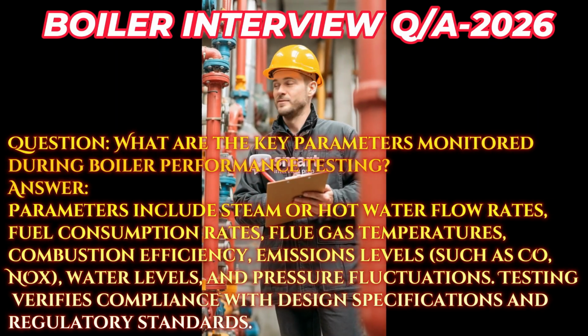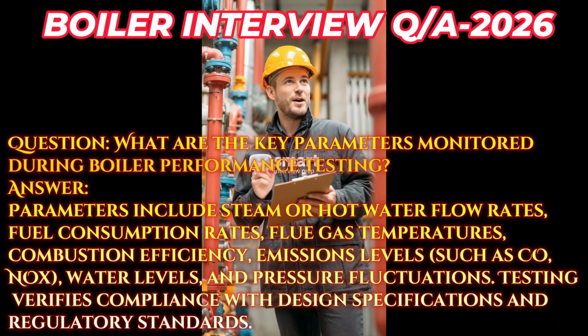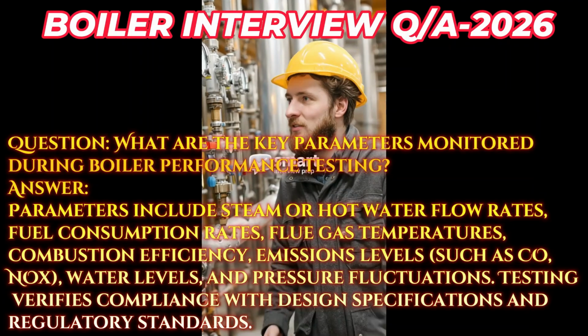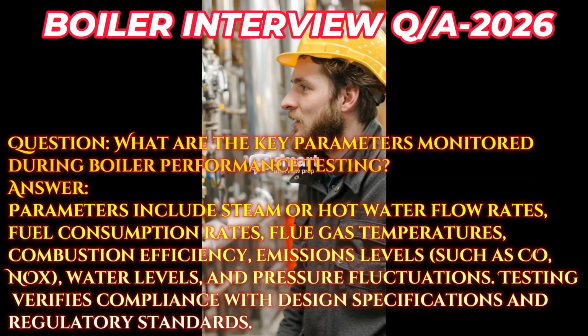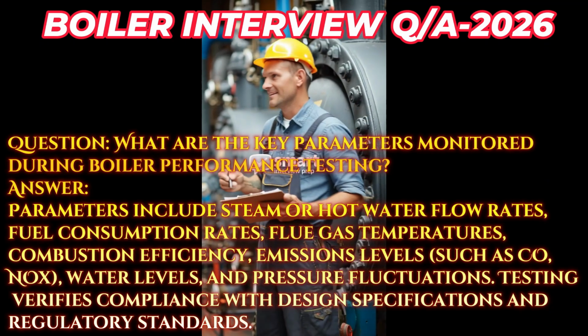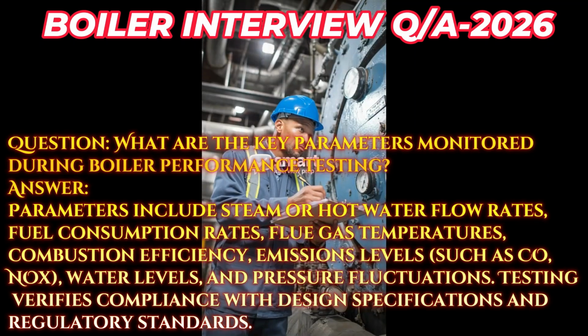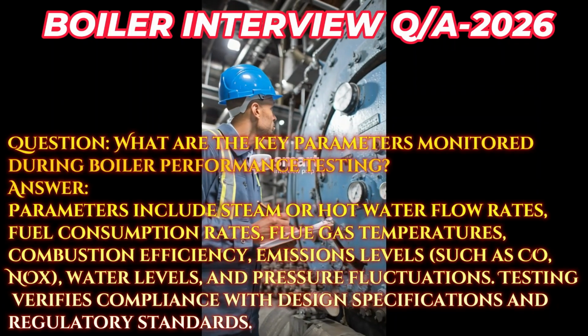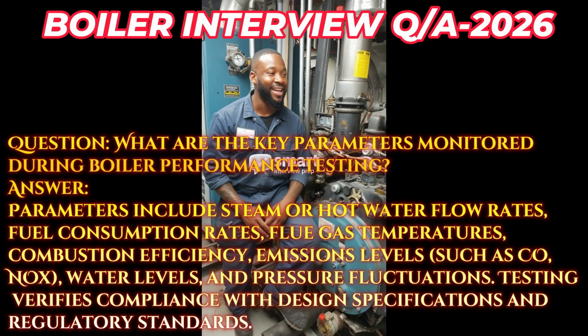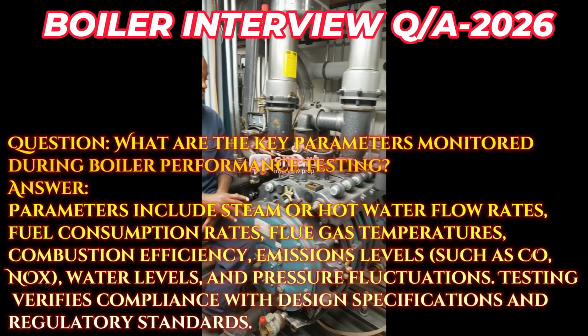Question: what are the key parameters monitored during boiler performance testing? Answer: parameters include steam or hot water flow rates, fuel consumption rates, flue gas temperatures, combustion efficiency, emissions levels, such as CO, NOx, water levels, and pressure fluctuations. Testing verifies compliance with design specifications and regulatory standards.